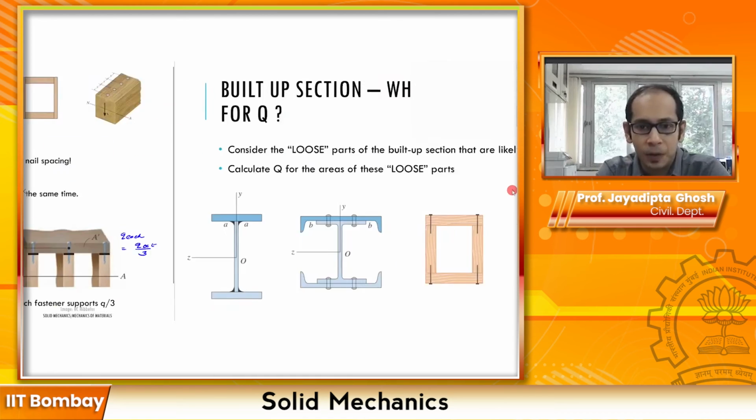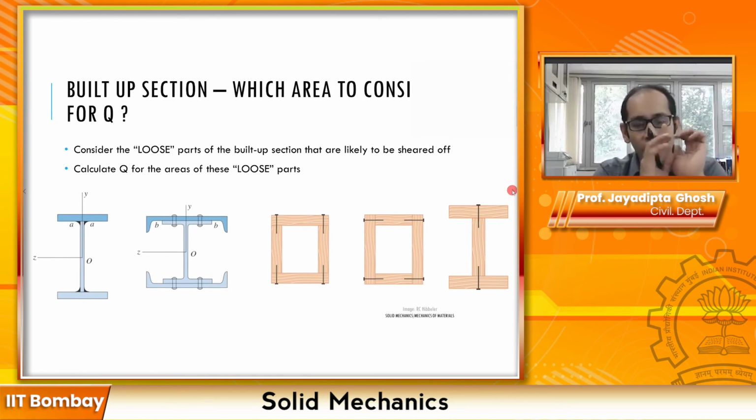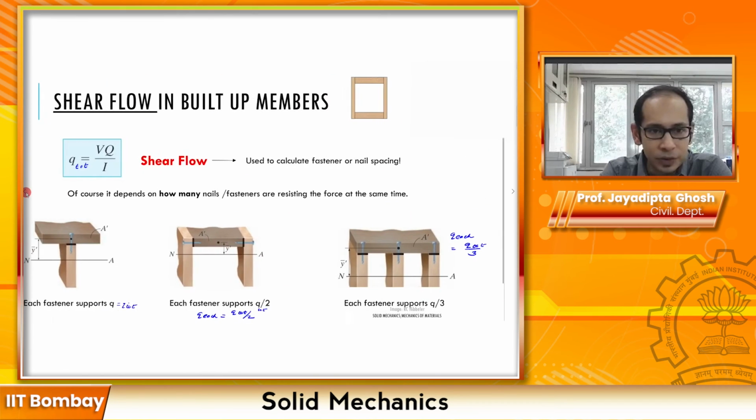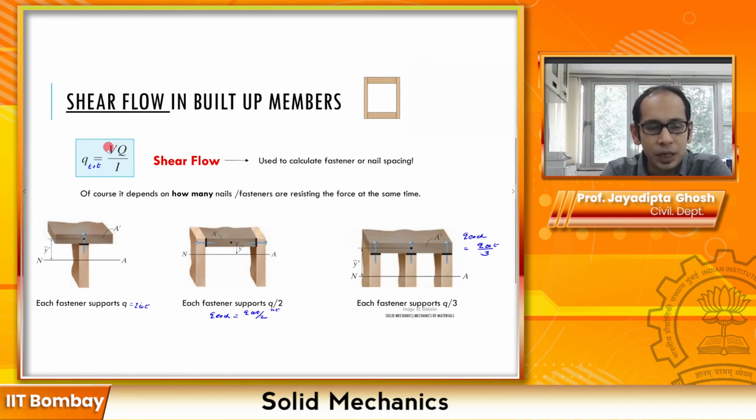Okay, all right. So now one of the questions is, let me go back to the previous one. One of the important things here is that in this formulation, this V is the total shear force that is acting across the section that is here. So across is the entire section V. I is always for the entire cross section, not a part of it.